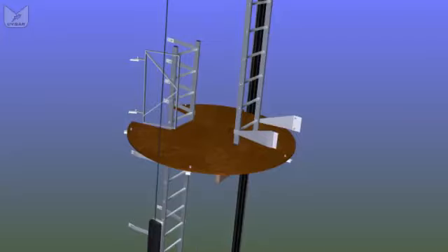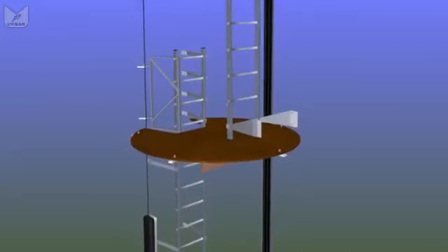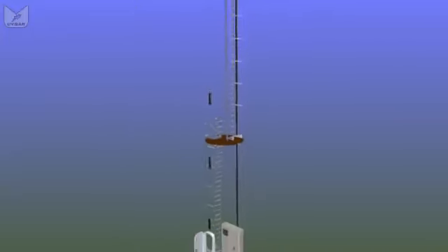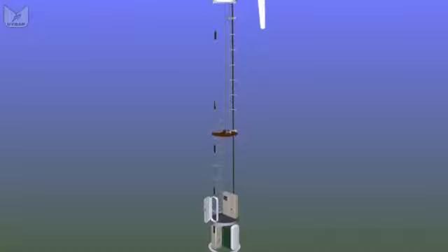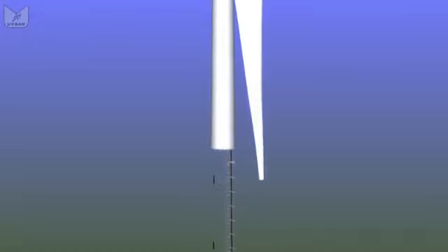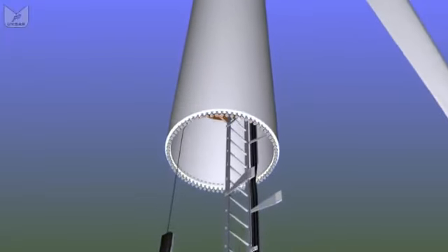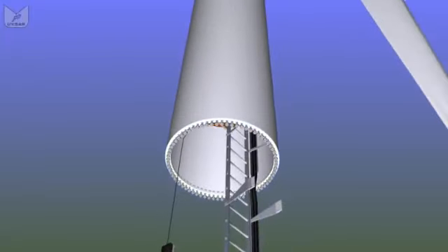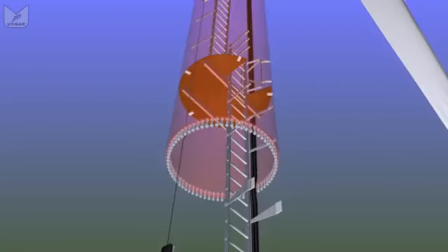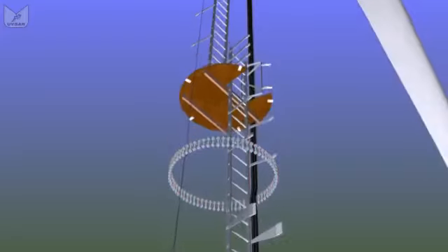The main run of cables goes up the wall of the tower, dodging past any intermediate junctions, because obviously the towers can't be delivered in a single 40-metre long section. They come in 20-metre long sections. They're bolted together with a lot of nuts and bolts. But as we move higher and higher through the platforms, they're getting slowly narrower and narrower, so the ladders are getting a little bit closer together.